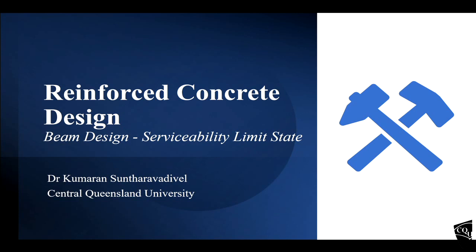But the important thing is the dead load is self-weight. So if you want to calculate the self-weight of the beam, you need the dimension. If you don't know the dimension, you can't calculate the dead load. So to start the design, we need to assume some dimensions.